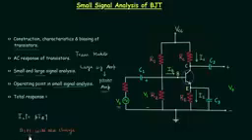We do not want the operating point to change or shift, but we do not have to worry about this condition, because this condition arises in large signal analysis. In a small signal analysis, Vs is small and IB will not change much, and hence IC will also remain constant and the operating point will not shift. So we can define a small signal as the signal having magnitude sufficiently small to keep the transistor in active region. This is the definition of a small signal. I will repeat it again. A small signal is the signal having the magnitude sufficiently small to keep the transistor in active region.